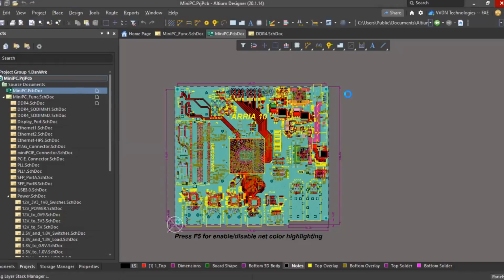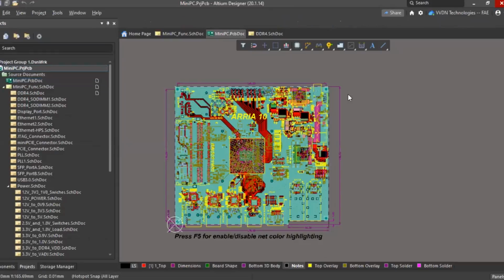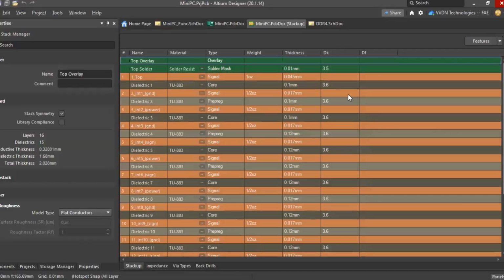And we have a material library so that you can easily select the materials, because many of you know that we are going with FR4, right? But when it comes to high speed, you have to select your material. It can be a different material type, right? Not FR4. Some other materials are also there, Rogers and, I forget that name, but other materials for high speed designs, you have to follow the material name, right?